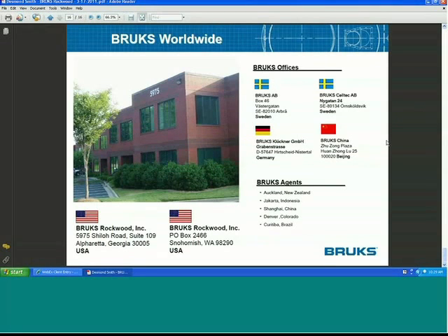Yeah, well, we do have some presentations, and there's an amazing improvement in the efficiency of the precipitator just by that reduction. And also just in total enthalpy and so forth. When you see this big steam plume going out of an FGD scrubber, you're looking at lots of wasted heat going into evaporation there.